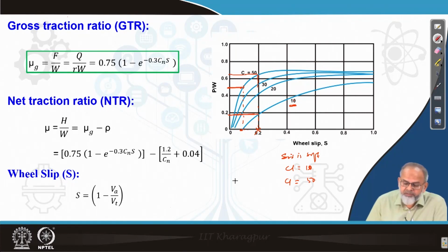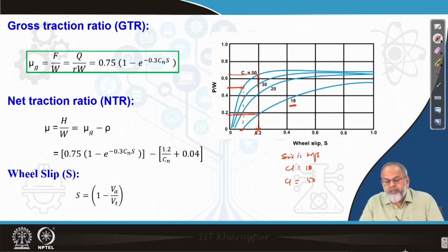That means, in hard soil, the tractor is able to develop more pull. In soft soil, the tractor will develop less pull, because power is lost in overcoming the rolling resistance. So, the net pull available will be less in soft soil, whereas in hard soil, the rolling resistance is lesser, hence the pull developed will be more and the coefficient of traction will be more.